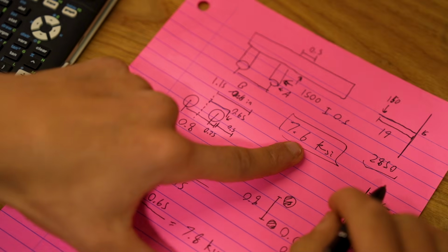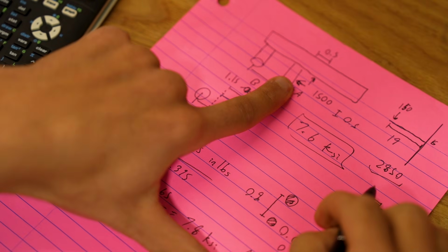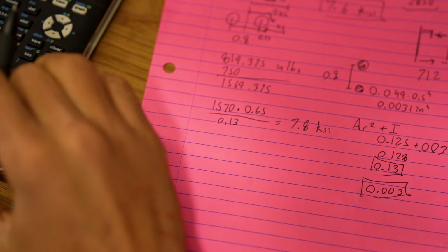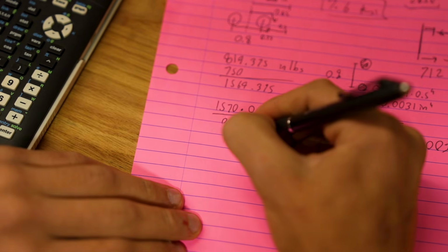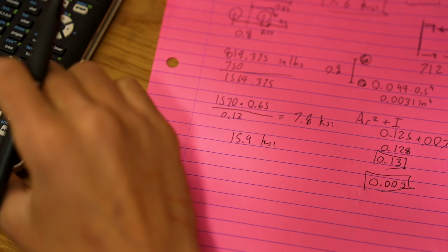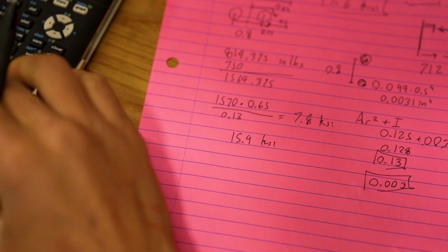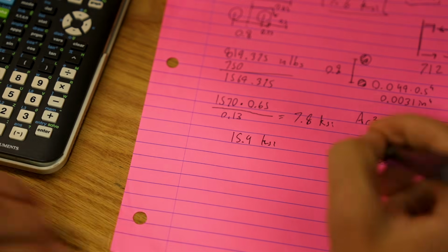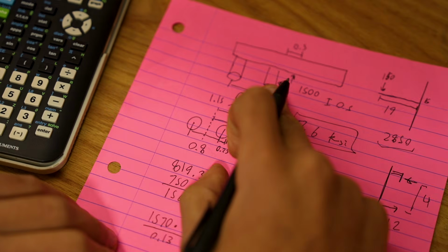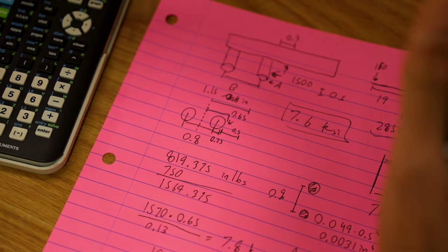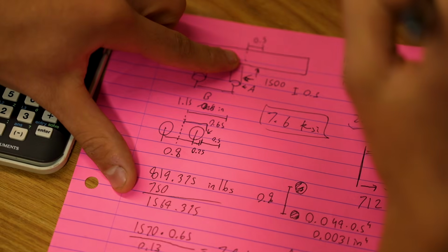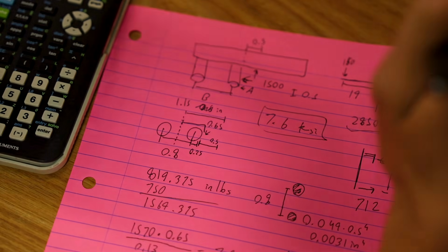We're also going to consider our shear, right? This one bolt is experiencing shear as well. So we're going to add that, plus we get 15.4 KSI, which if we divide 140 by 15.4, we get a factor of safety of 9. Bang. So our bolts are now validated. The last thing we're going to do, I apologize, there are a lot of pieces here. Last thing we're going to do for the hook, there's actually one thing after this,